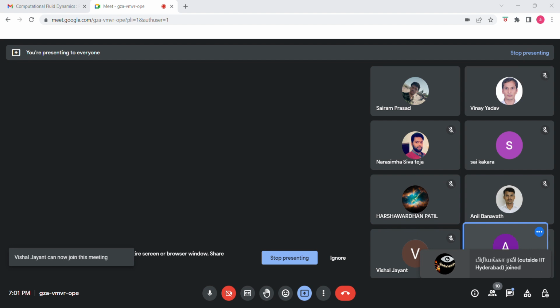Over 50% of time spent in industry on a CFD project is devoted to definition of a domain geometry and grid generation. Which one will be the reason for this? More grids will give better results. Calculation time is directly proportional to number of cells. To generate non-uniform grids. To generate an optimal grid with a compromise between desired accuracy and solution cost.